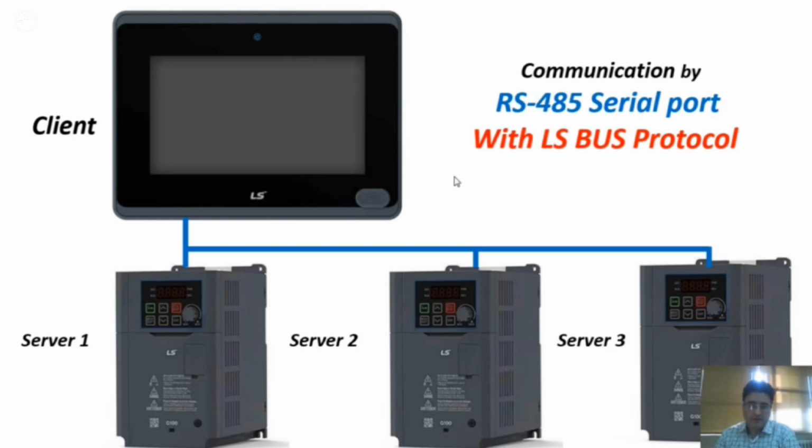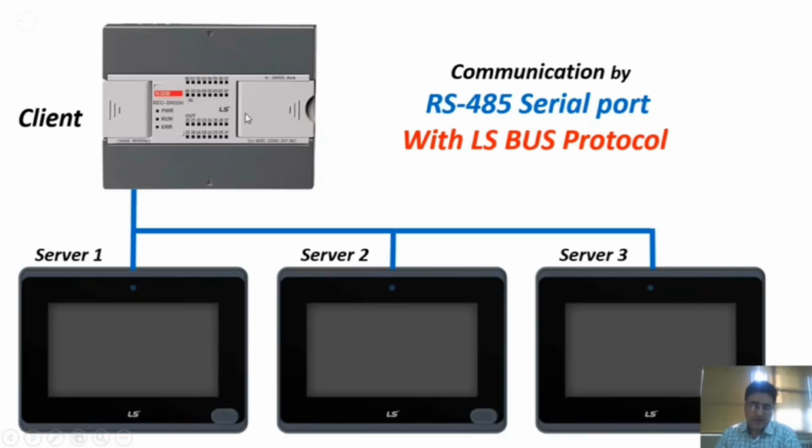One of the most common and practical applications of HMIs is effectively networking several inverters with a single centralized HMI. If all our inverters are exclusively of the LS brand, we can conveniently utilize the dedicated LS bus network, which specifically means we employ the robust RS485 serial port, along with the proprietary LS bus protocol. This advanced setup reliably allows us to seamlessly connect and manage several inverters simultaneously, providing comprehensive control and monitoring capabilities. We can be networked with a single dedicated HMI, or alternatively, we can connect several individual HMIs to an LS PLC through the efficient LS bus communication protocol.